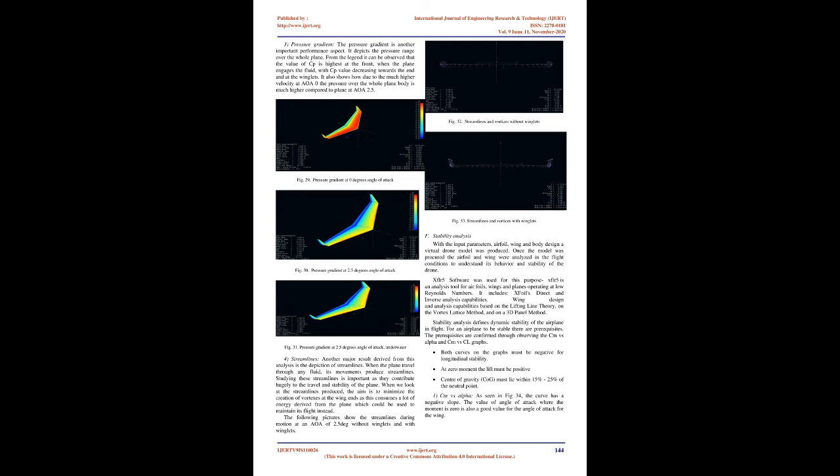D. Design of body. The wing body contains the major components of the airplane. The components are the battery, ESC, wiring, Pixhawk and extra weights to balance the center of gravity. Dimensions of the wing body depend on the dimensions of the listed components. The largest dimensions are of the battery, so the design is based around it. A CAD model from the resulting wing and body design, with a few required modifications for the wing body, was modeled on SolidWorks. Figs. 16, 17, 18, and 19 show the stages and views of the design. Final dimensions of wing and body are mentioned in section 7.